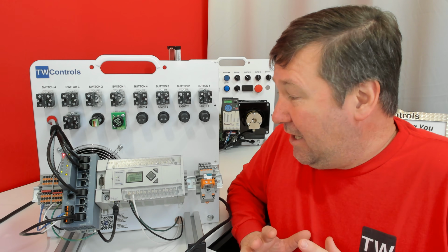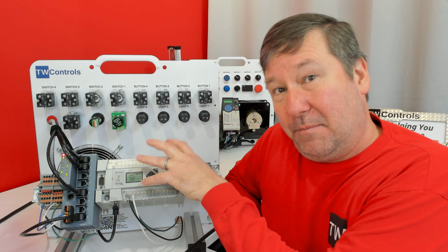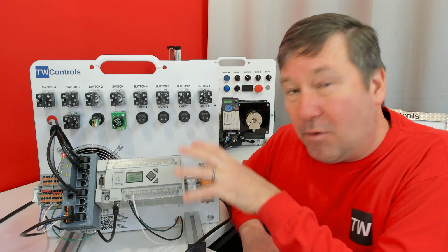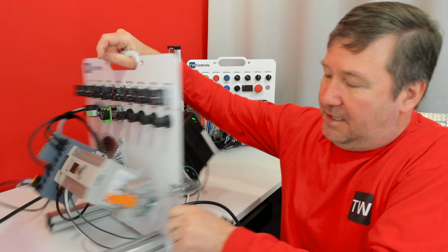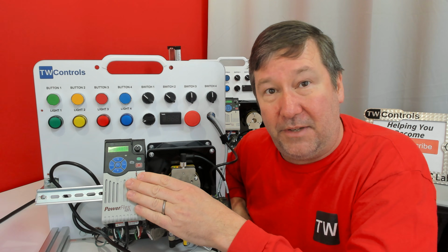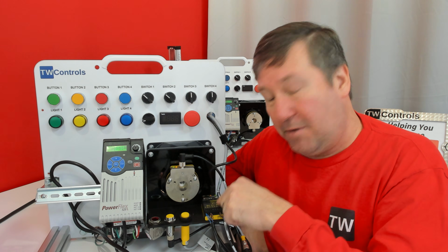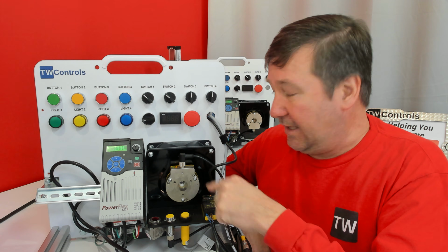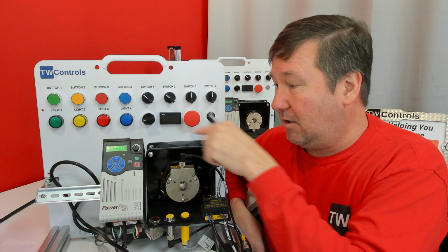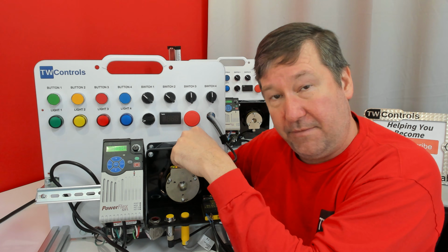In our previous videos, we've learned a lot about how we can gather and control devices over Ethernet with either the Micrologix 1100 PLC or the Micrologix 1200 PLC. And specifically in this case, we are now able to control our PowerFlex 525 over Ethernet with our Micrologix PLC. And we were able to connect over I/O link to this encoder. So now we have an opportunity for a closed loop control system because the drive is controlling our three-phase fan.